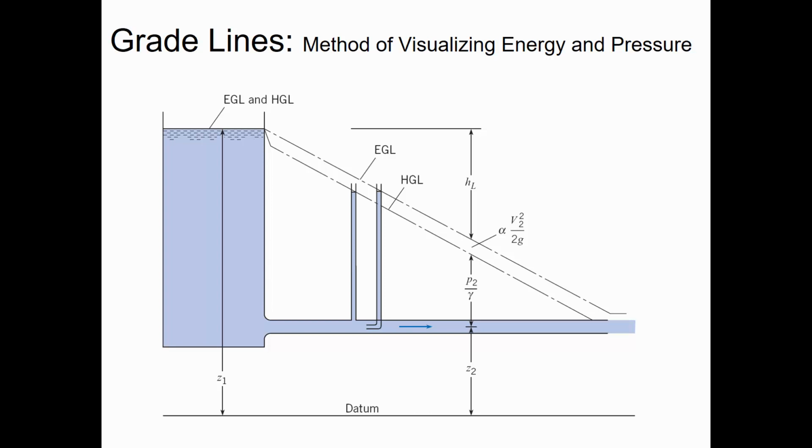But the tube that's to the right of that piezometer, you can see the water level is a little bit higher. And in fact, even though it's further to the right, the water level is a little bit higher. And that's because, as you might guess, instead of just having the tube connected to the side of the pipe, this tube is facing the flow, and so there's flow that's intersecting the opening of that, and we have a streamline that's dead-ending, and so that velocity head is exchanging into additional pressure at the stagnation point.